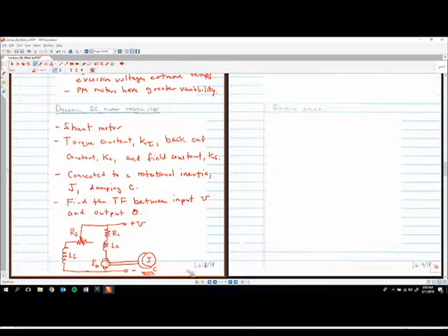Okay, in case you didn't see this in previous books, this is how I usually denote a rotational damping. Usually when we see these sideways lines here, this means that this is the earth or something really rigid. And then oftentimes for damping you'll see a bunch of X's in between. That represents either bearings or also oftentimes oil in between.